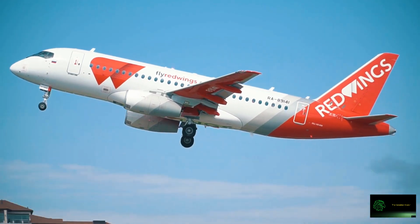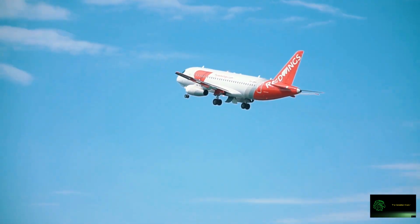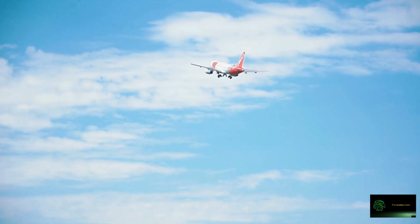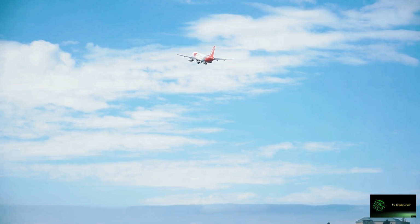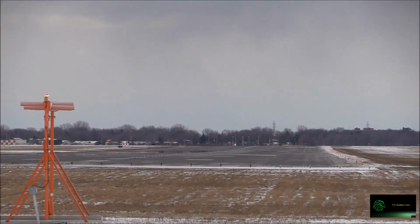This means that V1 is the maximum speed during the takeoff roll at which a pilot can recognize an engine failure and still safely stop the aircraft within the remaining runway. However, once the aircraft passes V1, the takeoff must continue, even if an engine fails, because there is no longer enough runway remaining to stop safely.